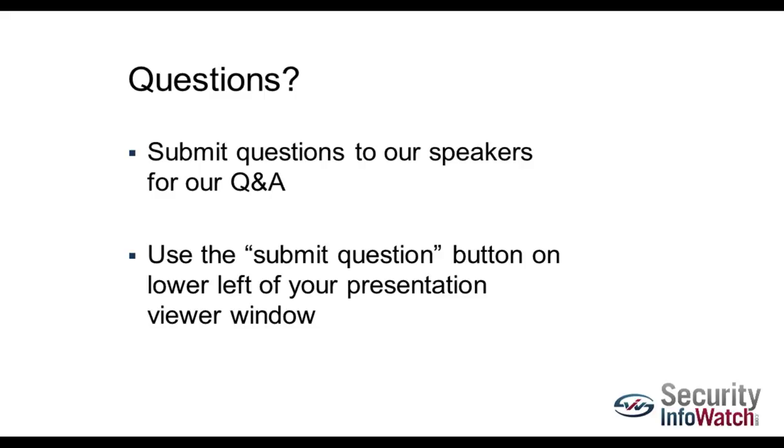Yeah, I can take that, Steve. You're absolutely correct that the reader panels normally will continue to operate. They have an internal database, and so the card readers and door strikes will continue to operate. However, we can't make updates to those in most cases unless the server is online. So we can't add or remove card holders, and we're not going to be monitoring that from any location either. So yes, the doors will continue to operate, but we can't change anything.